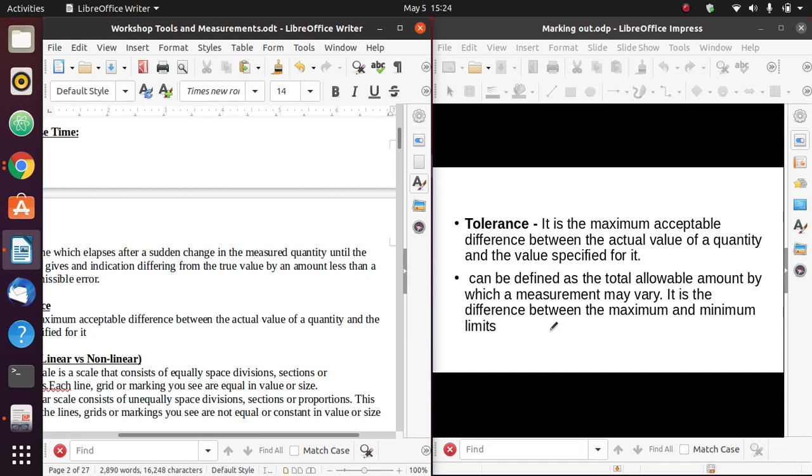And that's why when you're making whatever you're making, as a good engineer, as a good craftsman, if I'm going to be cutting a piece of metal, then I have to take into consideration that allowance. If I want to cut 10 centimeters in my workpiece, then I won't cut exactly 10 centimeters. I'll cut maybe 10.2, 10.3. I'll give myself that allowance so that in case there is any mishap when I'm cutting or when I'm machining them, I can have some room to rectify the issue.